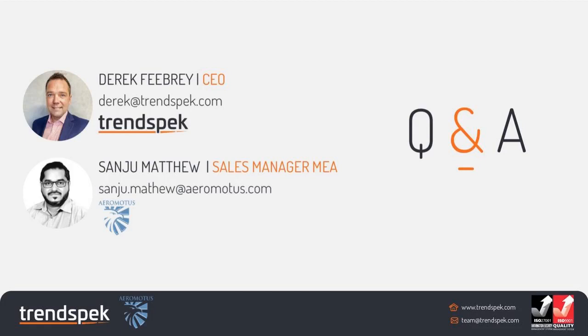Derek, there's a question. What type of sensors are available on board for the geotag 3D reconstruction? So I believe that you're talking about the M300 sensors. M300 is an RTK-enabled drone, so you have a built-in RTK antenna on the drone, and you have an RTK base station which comes along with the drone. So the position data on the images are georeferenced while you capture the images, and then it's a straightforward upload of images. You generally do not need any ground control additionally. I hope that answers the question.